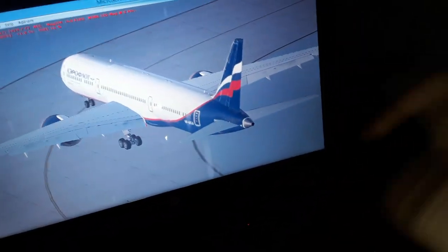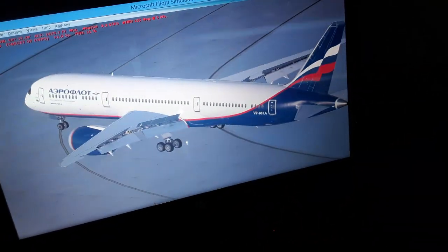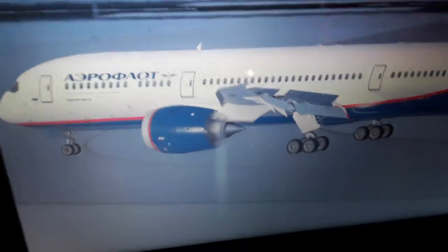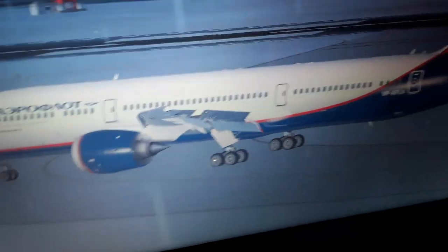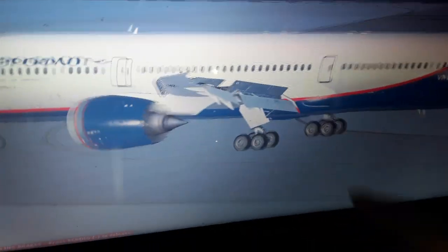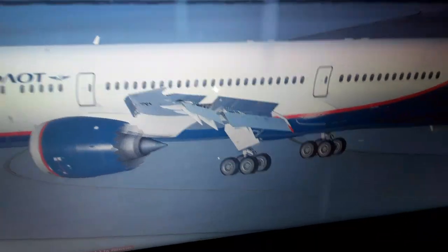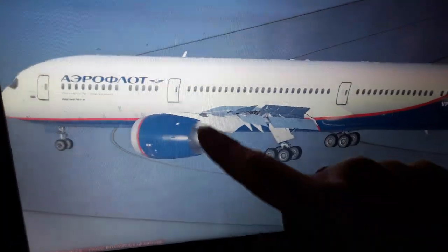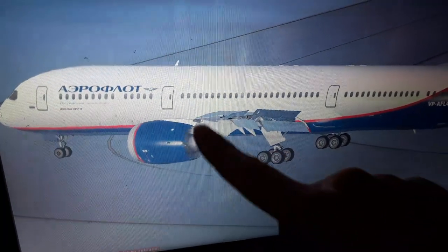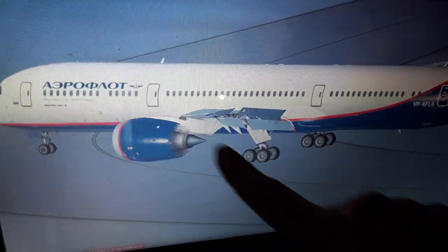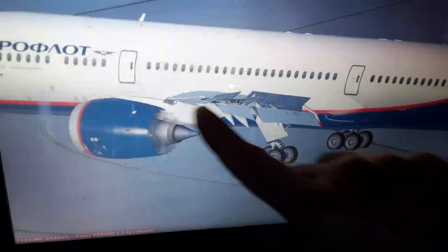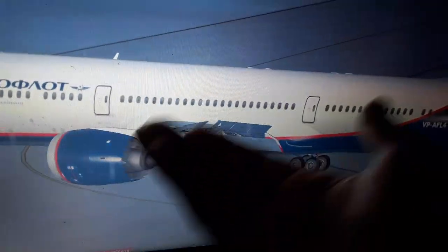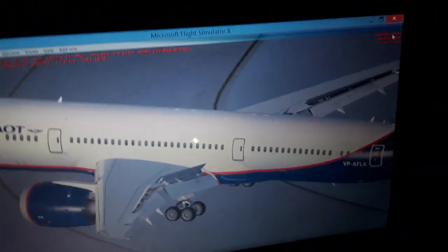Also we can see the bottom surface of the wings over here. You can see it is more flat, finishing the aerodynamics. So you can see also the flaps are extended, so the bottom surface, as we accelerate for takeoff like 250 kilometers an hour or 140 knots, there is higher pressure, the airflow moving slower below the wings, so higher pressure, which pushes the aircraft weight and wings up into the air.